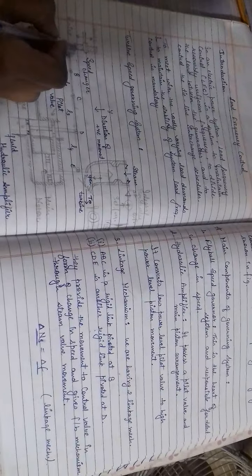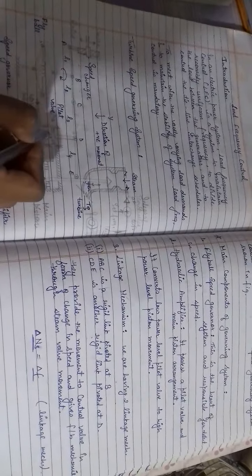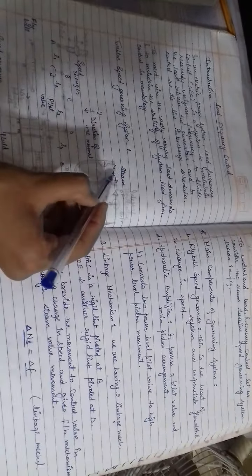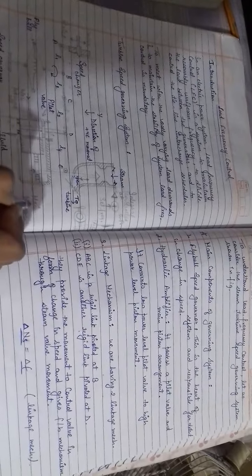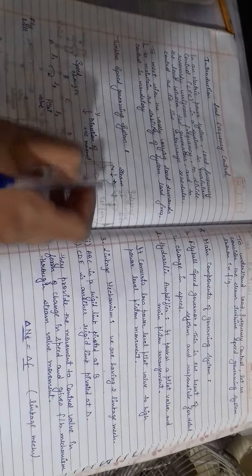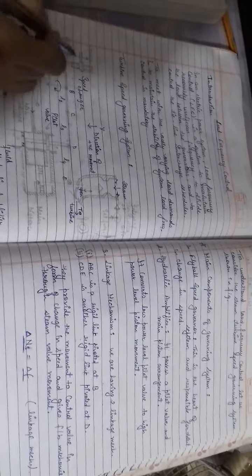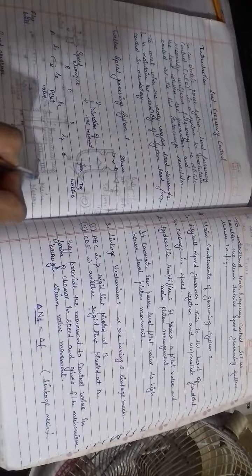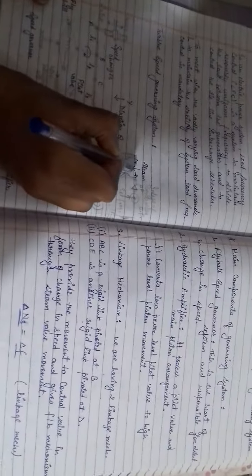Its downward movement opens the pilot valve. Downward movement means the speed increases, and the pilot valve will open, and the main piston will move downwards, and steam will enter the turbine. If the speed changer moves outwards, the pilot valve will not open, so the main piston will not move, and steam cannot enter the turbine. So we are changing the speed.